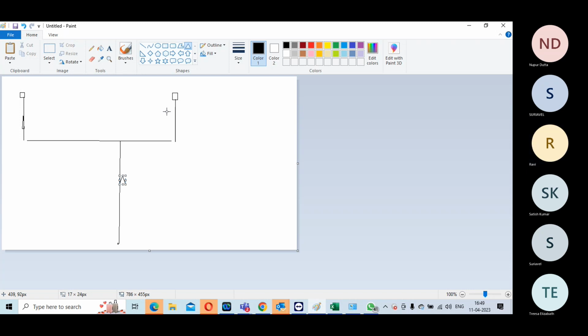Then you do hold buffering, again not at the end point, but at the start point. Start point hold or critical point hold fix. These are all tools which can do it. One hold fix can fix 10,000 violations like that. You understand? So first play with the skew, then you play with the start point hold fix, then you go for the bottleneck fixes, then you go for the end point.